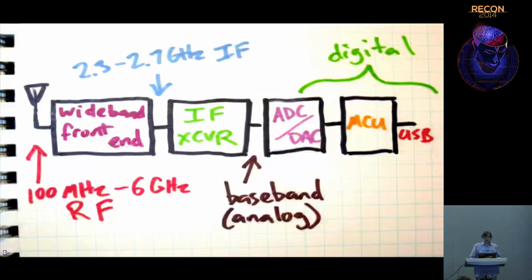Another thing to keep in mind is that arguably, instead of plugging into the front end like I did for that RFID demo, I could have plugged into the analog baseband. And at that level, I have much flatter performance down to the vicinity of 0 hertz. So that's arguably a better way to use HackRF at those frequencies. I just wanted to see how far down in frequency I could go on the RF, and that's why I did it that way this time.